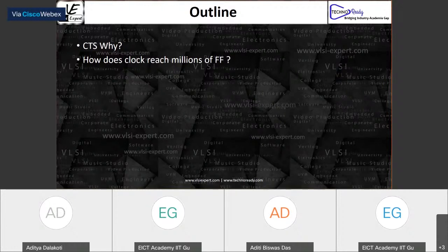So that is why you have such powerful open source tools with you, right? Get that experience. Try to build different clock trees. Try to see if you were able to successfully do it for a given skew and slew. You can do all that. Absolutely. And if you insert too many clock buffers, it also creates problems from congestion, crosstalk, and all that perspective as well. So there is a trade-off there.